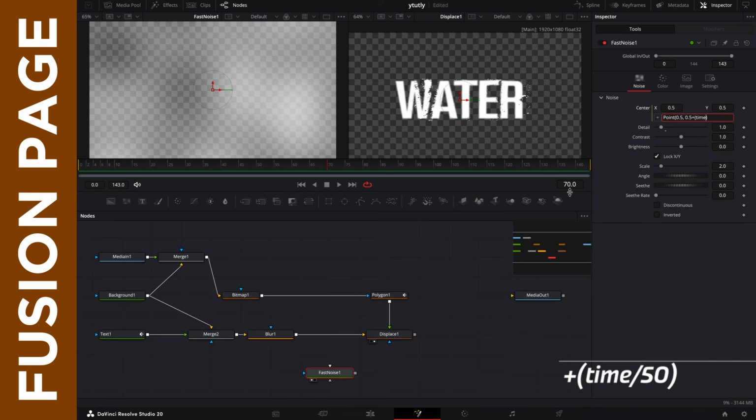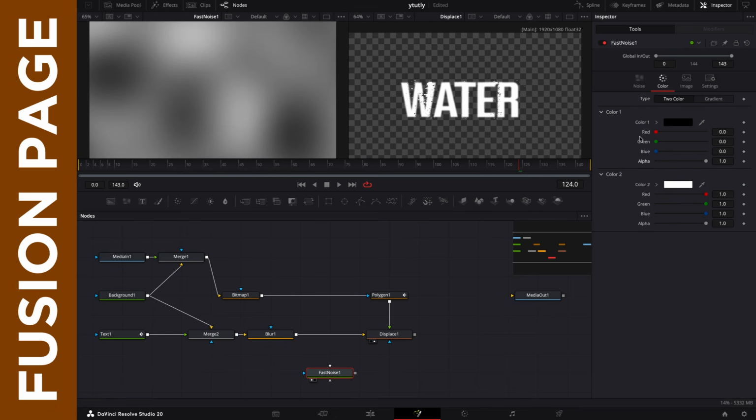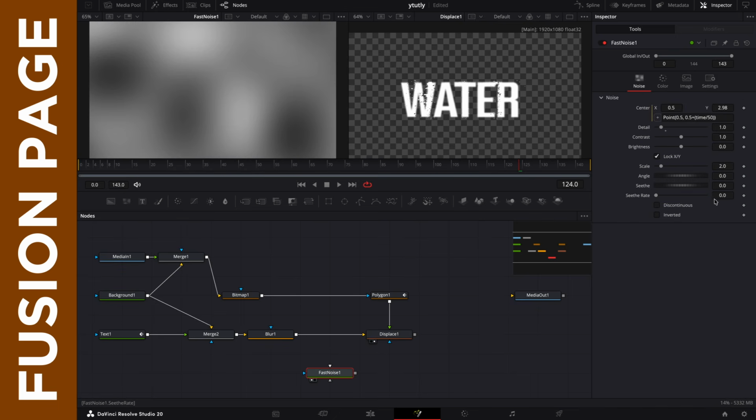So if you're on frame 70, this time will be equal to 70. Then time divided by 50. Then close bracket, enter. So that way, you keep looking at this left frame. If I drag this timeline, you see that thing moving up as the timeline moves forward. I also want to go to the color and set the alpha. I go back to noise, set the seed rate to 0.2.